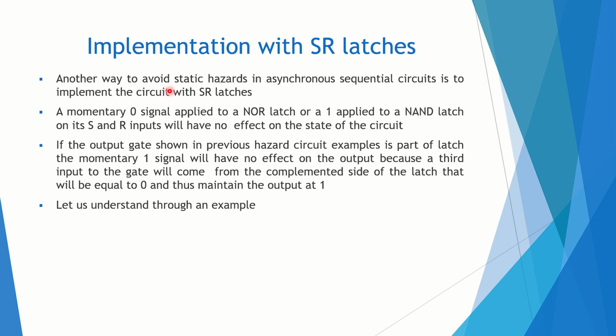So another way to avoid static hazard in asynchronous sequential circuits is to implement the circuit with SR latches. Why? Because a momentary 0 signal applied to a NOR latch, or a 1 applied to a NAND latch, has no effect on the latch. Suppose a momentary 0 signal is applied to a NOR latch, it will remain in the same state, and a 1 applied to a NAND latch will also remain in the same state.